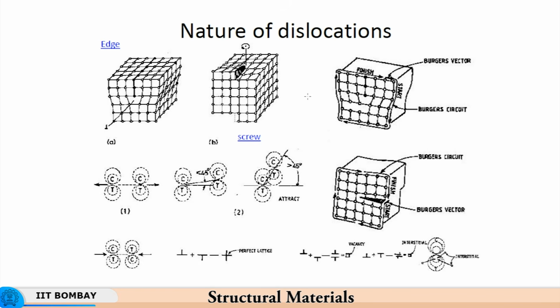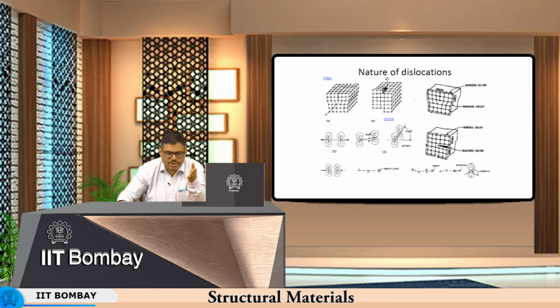So this dislocation is on one plane, this is on another plane, and when these two come together, the two stress fields are the ones which will repel each other. So if there is some angular difference between the two compression stress fields, then also the repulsion will tend to reduce.